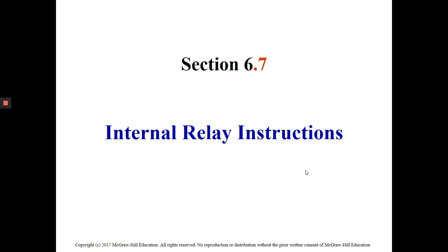The internal relay instruction is an instruction which does not control any output devices. So it's used to give you some virtual output. Okay, so we can use it within the PLC program to check the output of a series of input instructions.